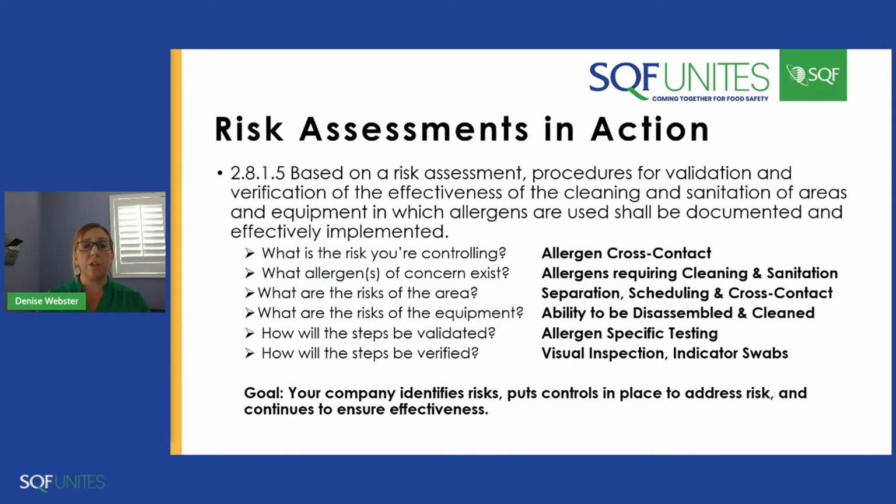We also have to look at what the risks of the equipment are. Does it have the ability to be disassembled and cleaned? How will the steps be validated? Are we going to do allergen-specific testing on the equipment? Are we going to test it? It's up to you. You have to determine those risks and then put the appropriate controls into place.